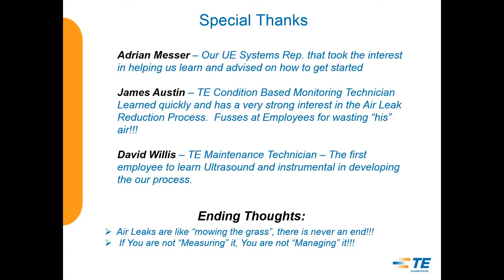Just a couple of thoughts. One of the sayings I've tried to come up with when I talk to our management and our accountants is this: they think that once you fix air leaks, they're done. But air leaks are a whole lot like mowing the grass. There's never an end. It's a constant battle. We can actually go 2 or 3 months without doing much air leak work, and we can see our compressor runtime starting to increase again. So it's a constant awareness, constantly being on the floor with the gun and constantly fixing those air leaks.